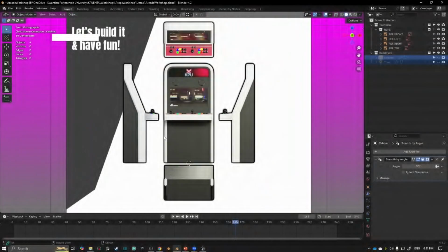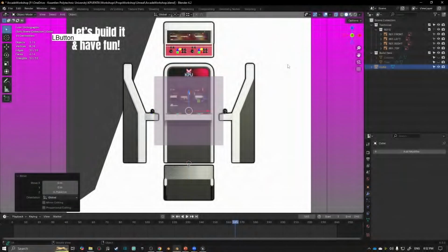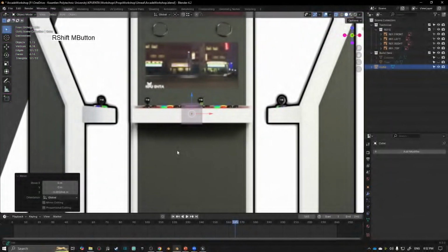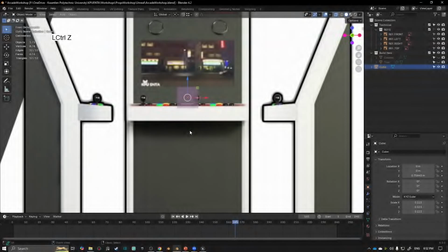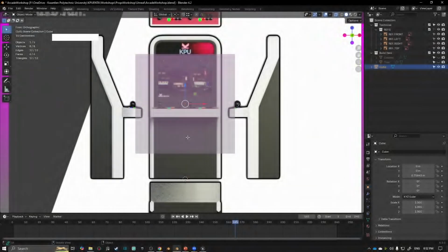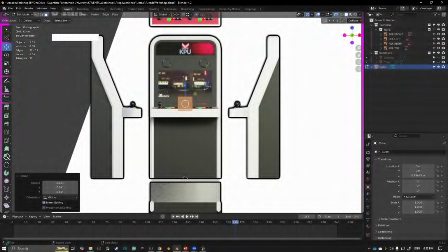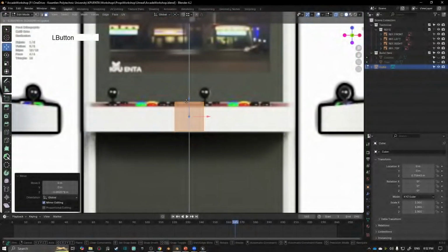Okay, now for the control deck, it's just a cube. So we'll go create cube. Again, it doesn't really matter what the size is, because I'm just going to scale it. So I'm going to scale it way down. Now, here, I scaled it as an object, which gives me funky scales. If I undo that, I go into Edit and then scale it way down. My object scale stays okay, which is much preferable. So sometimes, if you remember, just go into Edit first.